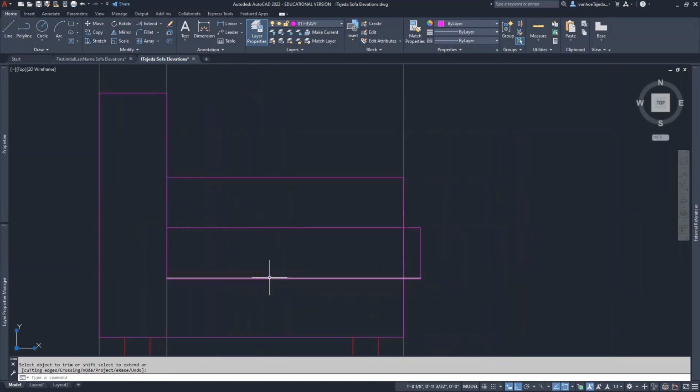The lines here are on the wrong layer because they need to be on the layer called light. So let me show you how I'm going to fix that. I'm going to select the objects, this one, and this one. I'll go ahead and enter. No, I'm not going to enter. Now that I have the 3 objects selected, I come up here to my layers and I simply move them, place them onto this layer. And now I can go ahead and tap the escape key.